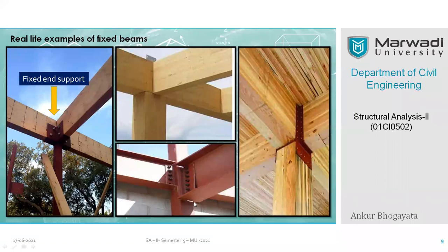And here you can see that it's not a 100% fixed joint. It is a partially fixed joint, because the bottom of this I section is free to rotate about the axis. So unless you provide some additional connection support in terms of angles, you can expect some deformation of this beam, and some rotation is expected.